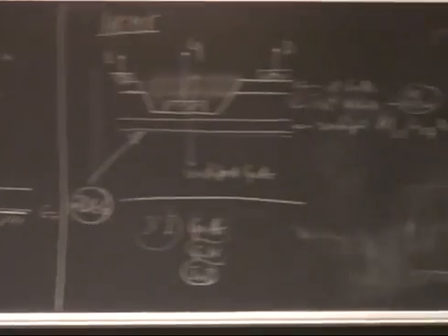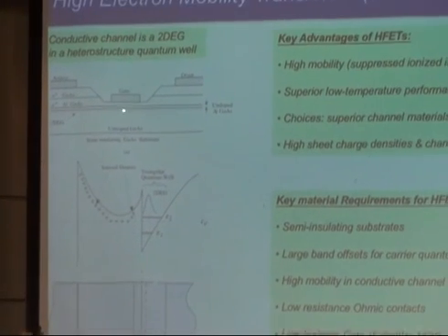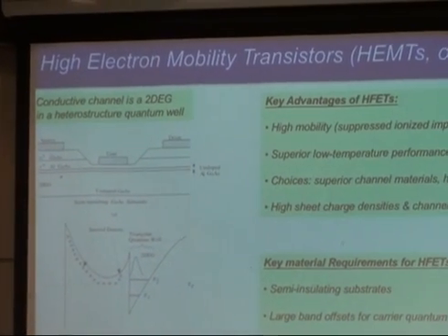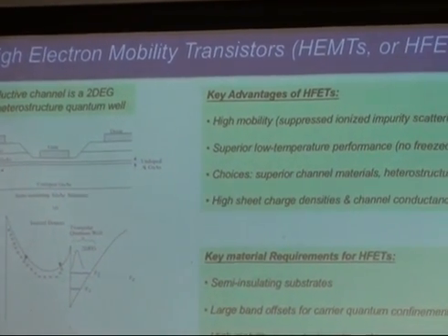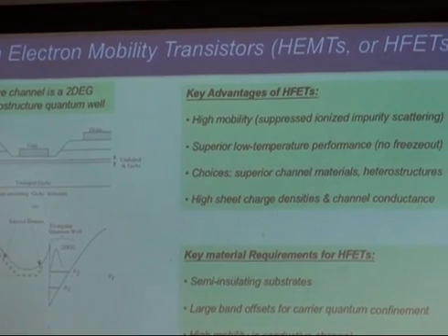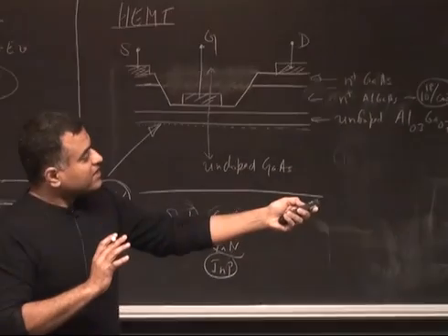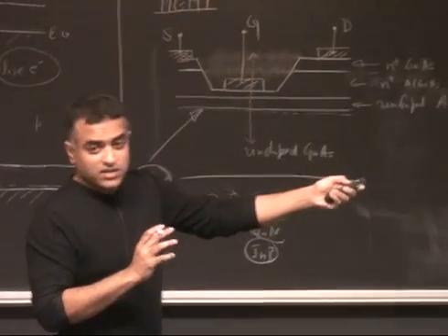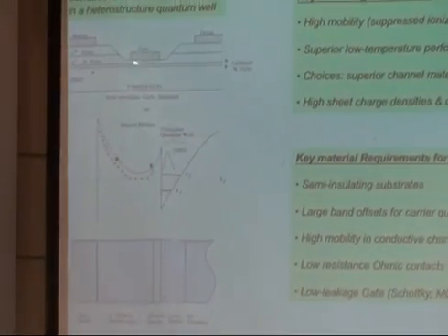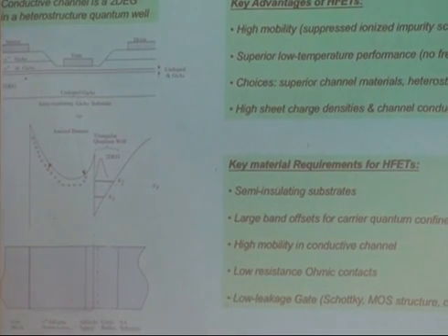The gain comes if the gate is coupled capacitively to the electron gas, but there is no electron flow here, because the gate can now control the resistivity of that region without flowing electrons into that region. So it remotely controls the resistance of this channel, right? It can remove or accumulate more electrons in that region. So it remotely controls the resistance of this, and that's, again, the origin of the name transistor.